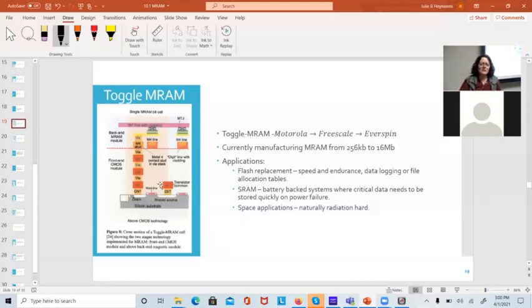Okay. Now, if you look at this processing structure, down here, I have what looks like a standard CMOS structure. I've got a transistor, or probably an NMOS transistor. I have a word line, I have a drain, the source, I've got the substrate, probably a FET now or something like that. And I want to put the MRAM on there. What I'm going to have to do is I build a stack of vias and metal going up to give me some mechanical spacing up here. And then I put a big metal core stud up here.